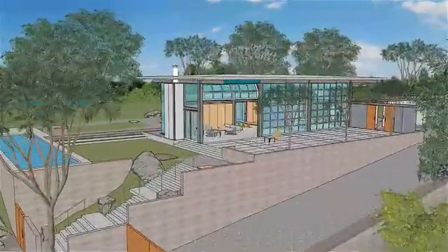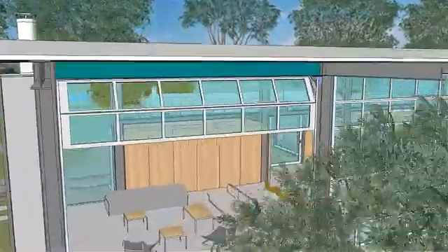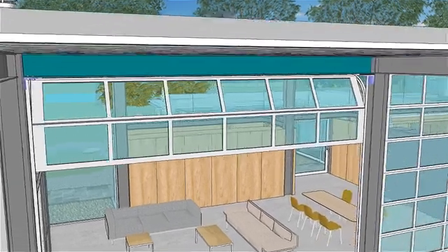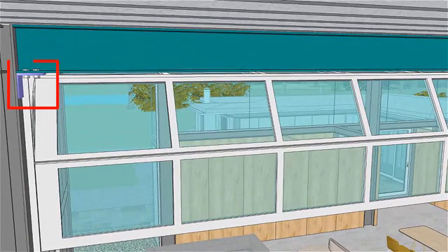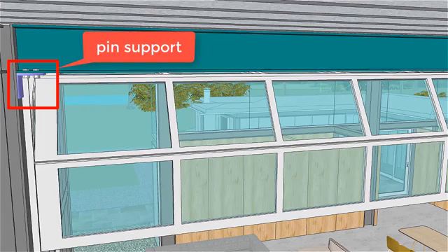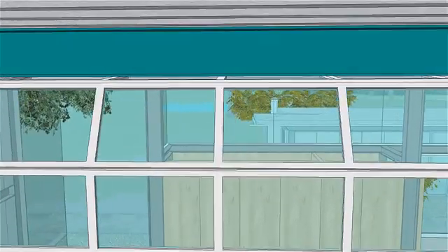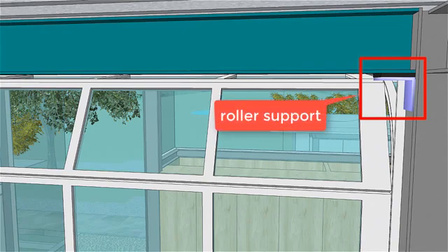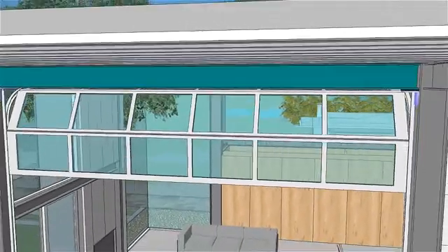Consider a particular beam in this steel and glass house. The beam is a member of the skeleton of the structure. At its left end, the member is seated on a plate and attached to it using a few bolts. We consider this a pin connection, since the bolts don't sufficiently restrain the end of the beam from rotating. At the other end, the beam rests on a friction pad, which allows the member to elongate, say due to temperature change. For the analysis purposes, we consider this to be a roller support. So we're going to treat the beam as being simply supported.